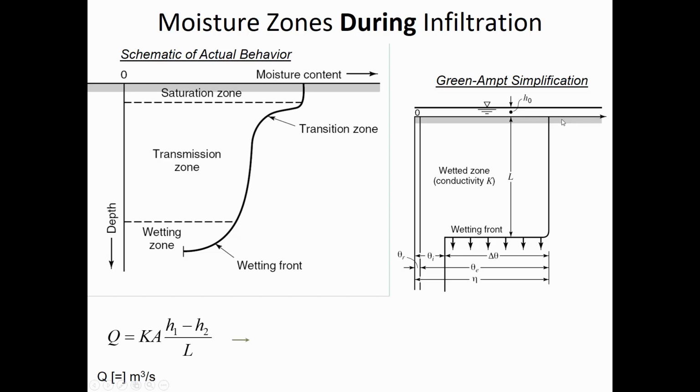And so if we think about what's really going on, it can be thought of in terms of Darcy's law. Remember, Darcy's law is the hydraulic conductivity and then some cross-sectional area that the water is flowing through, and then the driving force, where H1 and H2 is some elevation gradient between the upstream and the downstream location, and then L is the length over which the flow occurs.